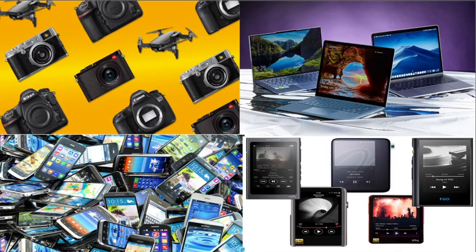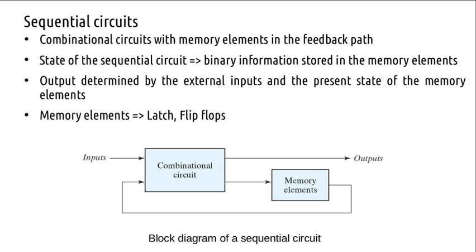But if you need something which is to be retained, a data bit has to be retained for some amount of time, then you need to have a specific circuit which has a feedback from the output to the input side. So cross coupled circuits. These are bistable circuits. Flip-flops are called bistable circuits because they have two stable states. So these have memory, right? So, sequential circuits.